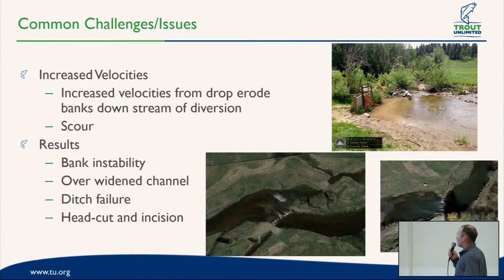And the other issue is, once you have that wide channel, when you're eroding this material from here, it's got to go downstream and essentially deposit somewhere, and that might create additional erosion. You get a mid-channel bar, for example, and the water wants to go around that and continue to erode banks.